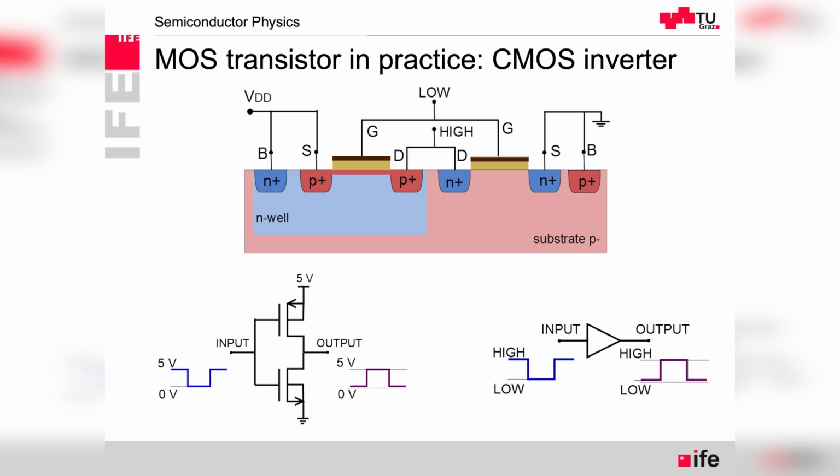In this case, it's all what we have learned about reverse bias diodes and the dark currents in the diode. In principle, if you want to have a good sample and hold circuit, having good properties during the hold time, it would be great to quickly cool it down for the hold time. No, it doesn't work. But low temperature helps with the leakage current.